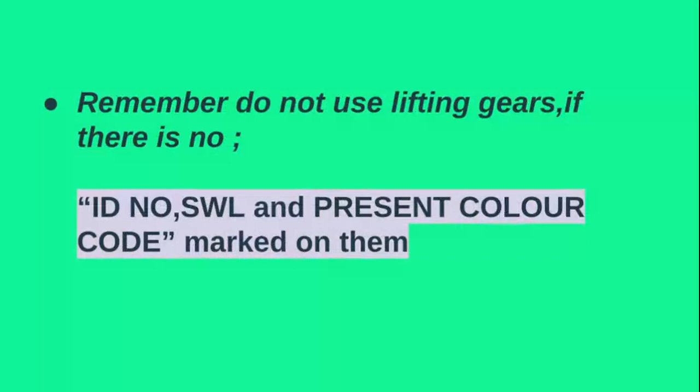So friends, don't use it. If no ID number appears, if there is no SWL, or if there is no present color code marked on the lifting items or lifting equipment, don't use that. Please consult your supervisor.